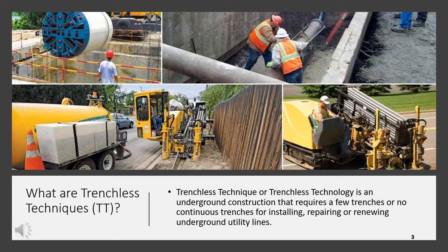Now, what are Trenchless techniques? Trenchless techniques, or Trenchless technology, is an underground construction method that requires a few trenches or no continuous trenches for installing, repairing, or renewing underground utility lines such as underground pipes, ducts, or electrical cables. Trenchless technique construction reduces traffic congestion because the methods can be carried out under a busy highway. It also results in less air and noise pollution, and this method of construction is also less hazardous to workers because it can be controlled from the surface.